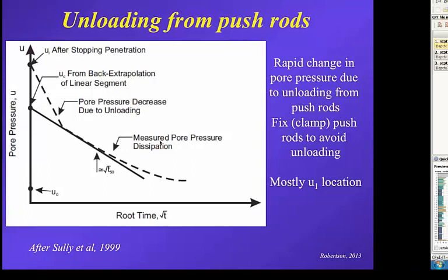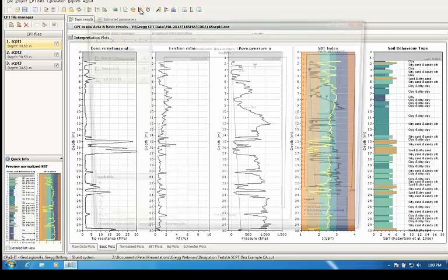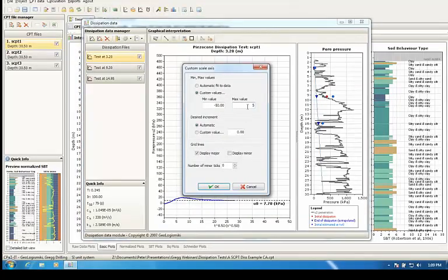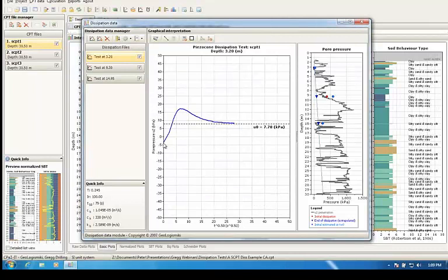So the profile here was some upper sand and then transitioning into a lightly over-consolidated clay. But right at the transition, there appears to be a crust on the clay, and this dissipation test appears to be done right there. So probably the clay right at this depth is more over-consolidated.